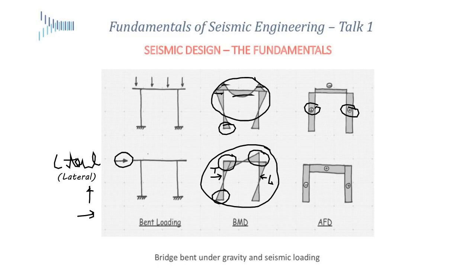So on the one side they add, on the other side they reduce the effects of each other. So if my lateral force is large enough, I might get a bending moment here which is so large in the positive sense that it overcomes this negative bending moment. Now, if I only have rebar at the top of the beam, I have nothing to resist this resultant bending moment, which is now positive or in the other sense. And that used to be one of the classic mistakes that people used to make because we didn't understand the phenomenon that well back in the day.